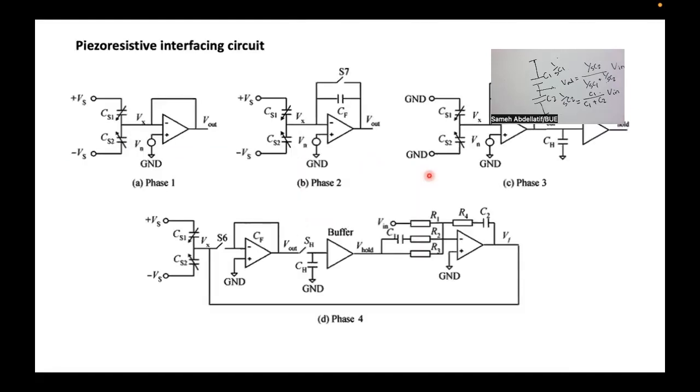As I just mentioned, maybe in the previous part, you cannot stop with having different topologies for cascaded systems. So here you can find a collection of capacitive interfacing circuits with different cascading topologies. For example, here we have a two-terminal voltage connected between two capacitors, and these two capacitors represent two sensing elements. And then we have a buffer. This is a typical buffer connected.